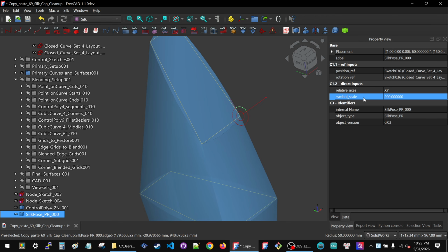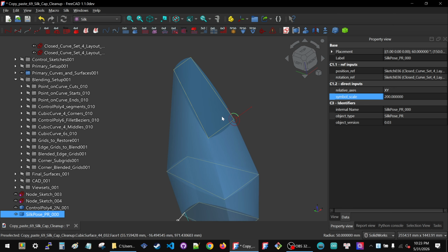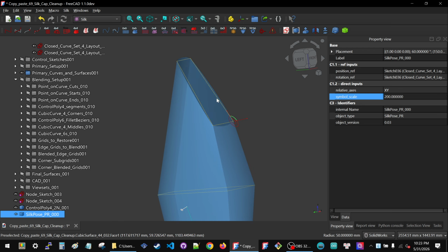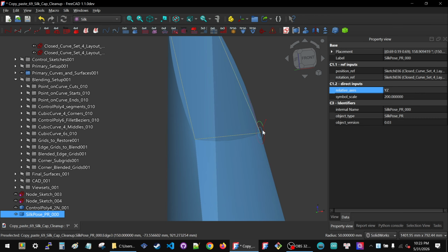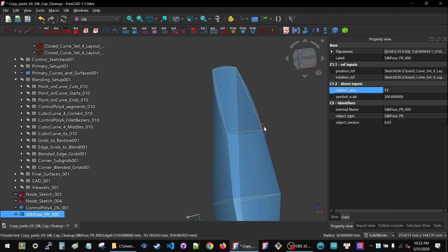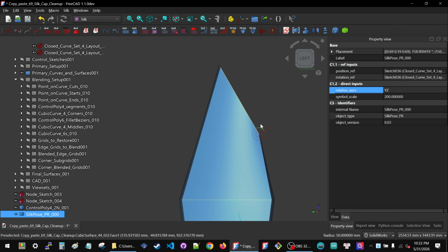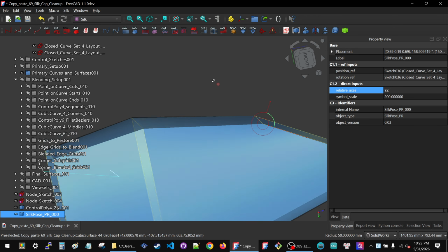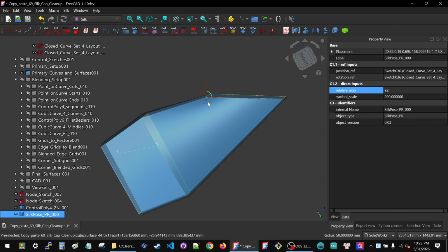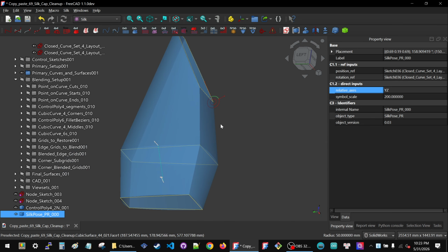And it said, well, right off the bat, by default, I'm going to translate the origin to the point you selected, and I'm going to use the relative axes XY of the object you selected. So I'm in the XY of this layout, but the origin has been shifted to the point I clicked. This is very neat. And right off the bat, I can say, well, now I want to be in the YZ of this object. Look at that. Now it gives me a plane in the YZ of this object, and that's actually what I'm going to use. I'm going to set myself in this plane to draw this curve.